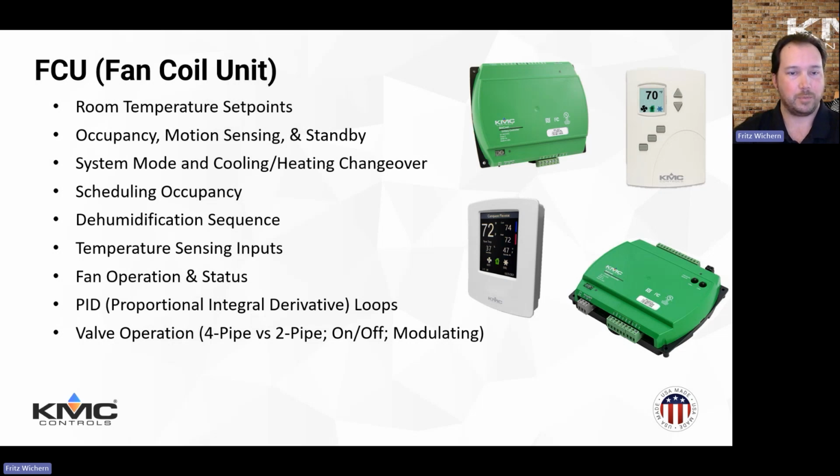Next up, we have our occupancy, motion sensing, and standby. Motion sensors are integrated to adjust room conditions dynamically, and the system transitions to a standby mode if there's no motion detected. So it's different ways to save energy there. The system mode and cooling/heating changeover are done based on set points and the environmental conditions.